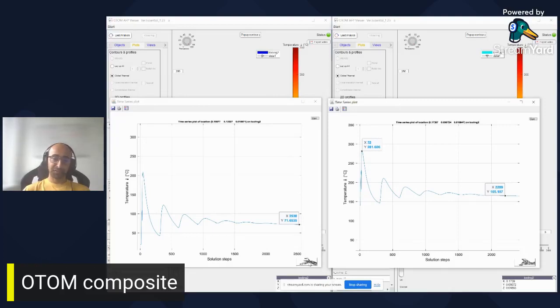So for the crystallization prediction, you could click on this animation icon, which shows the crystallinity. If you hover the mouse here, you will see the crystallinity. If you click on it, it will tell you what the initial crystallization is. You could say that you would like to see the progress only, so you put it as 0, and the time step of the process. It automatically uses the time step that was used for the analysis, but you could change it to see it for different process times.